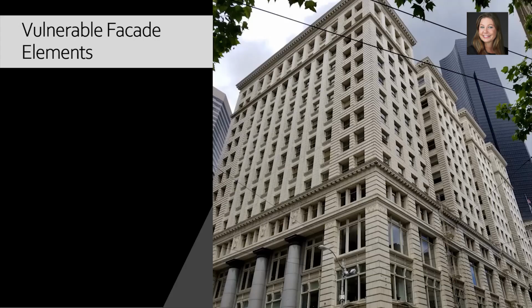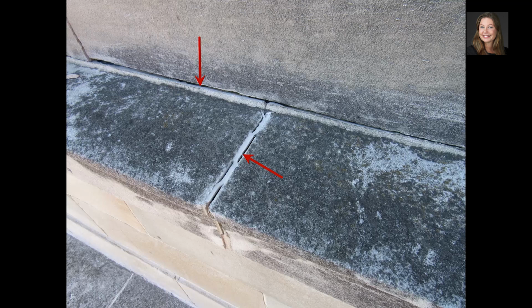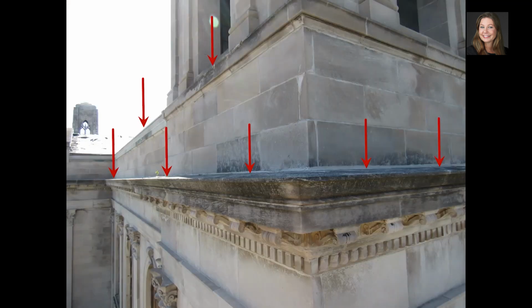The most vulnerable part of any facade is those horizontal, skyward facing surfaces. Things like cornices, parapets, belt courses, water tables, and windowsills. They are all like little mini roofs all over the building. If there is an opening on one of those horizontal surfaces, a debonded mortar joint or a debonded sealant joint, water can directly get in and it goes directly into the wall system. So it's a big deal to make sure those are protected.